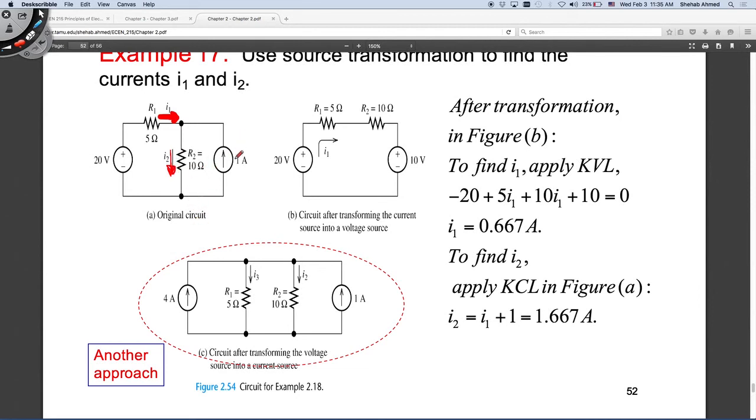So this is what? This is a current source with a resistor in parallel, right? How about I disconnect this from the circuit? I'll take it out. This looks like my Norton equivalent circuit of something, right? This is a current source with a resistor in parallel.